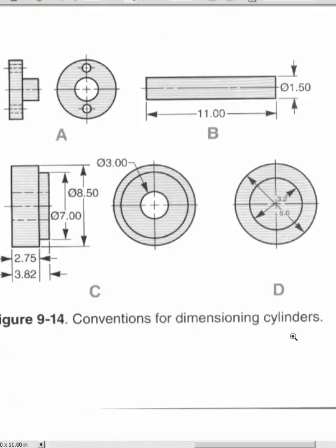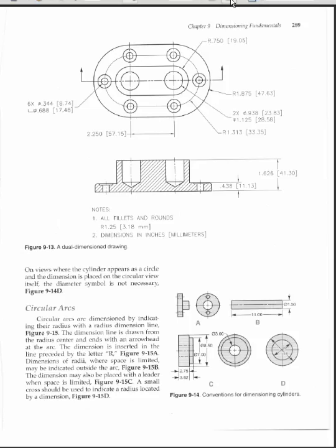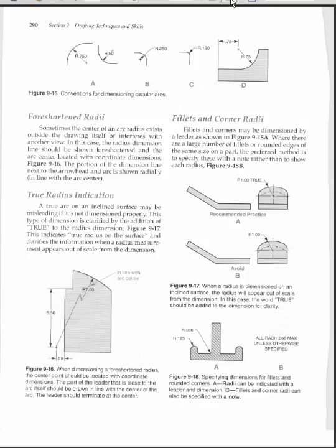Here's another case in point. When dealing with the stacked cylinders, again, when you can't see the circle face, throw the diameter symbol in front of it. And when looking at it from above, simply throw the diameter symbol there. And here's another format, however, that is not as easy to see as this one. So, that's how you handle cylinders. No problems there, right? So mark this page in your book somewhere that says dimension cylinders. That way you can find it easily and look it up.